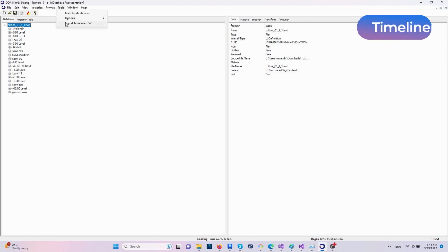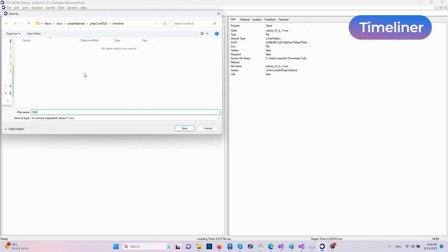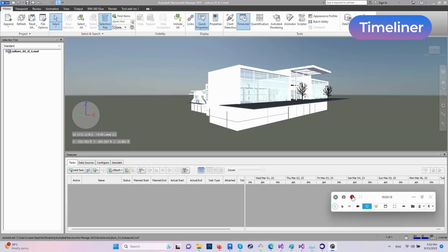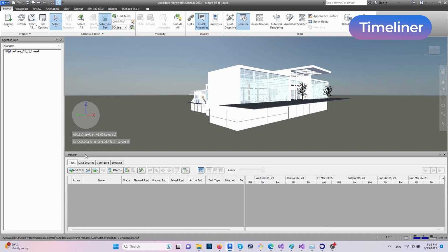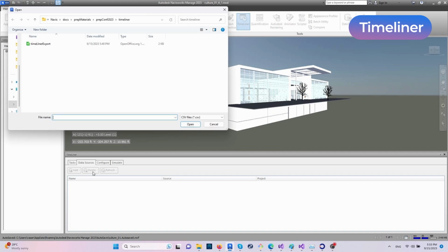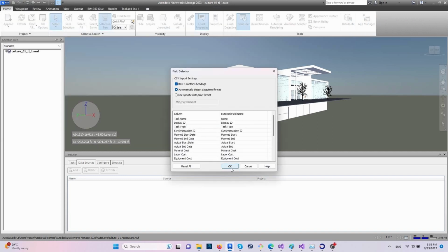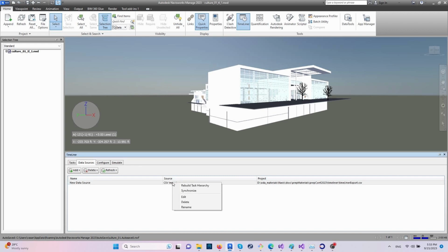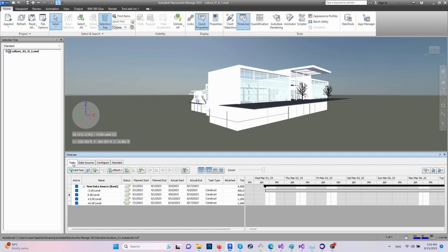Navisworks files are often used for time and cost estimations. To enable this functionality, in BimNV, we recently introduced timeliner support. The timeliner tool enables you to link a model to an external construction schedule for visual time and cost-based planning. In addition, timeliner data may be exported in CSV in exactly the same way as Navisworks itself.